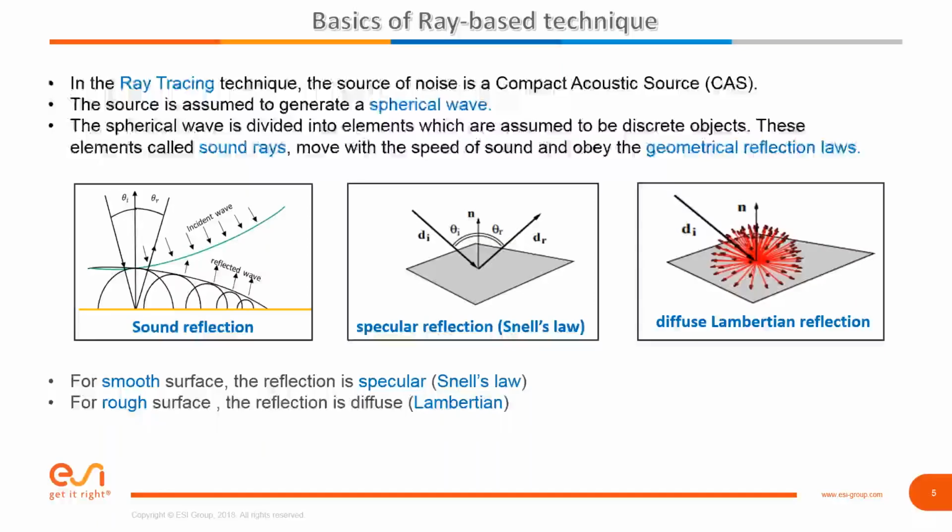One of the classic examples is to just look at a dipole instead of a monopole. And you can achieve a dipole by having two correlated monopoles. This is another way of looking and saying, hey, this is a simpler way to represent complex sources. Instead of a collection of correlated monopoles, a single compact source, usually spherical, not an absolute requirement. We can work with other shapes, but this is a nice flexible source, elegant. You can just describe as a single source, something with a very complex directivity, and other than being in the very, very near field, it's a good and accurate representation.